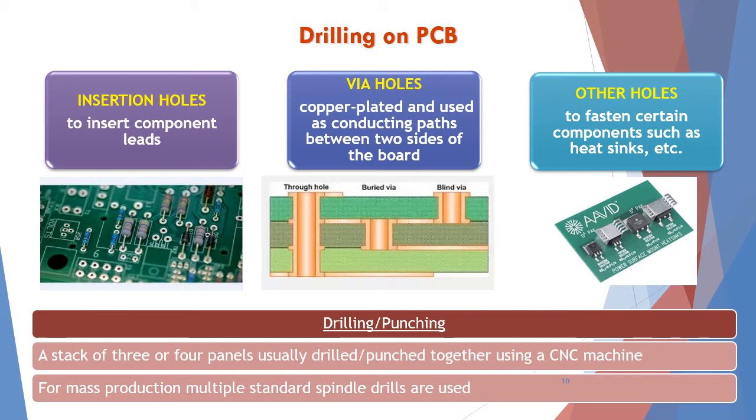However, for high-tech PCB, you cannot perform the drilling with stacking of panels. It has to go one by one. Okay, so for mass production, multiple standard spindle drills can also be used.